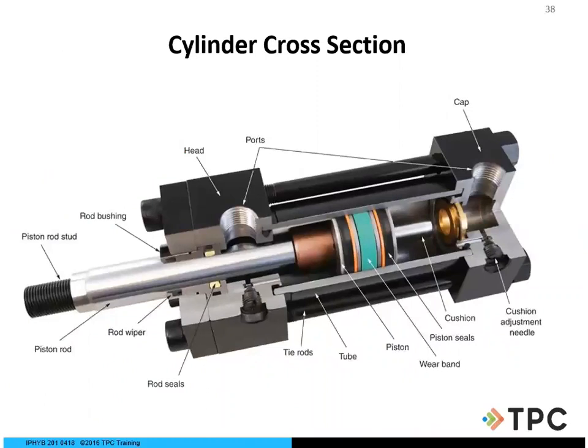And what about our actuators themselves? What about the cylinders? So we definitely need to maintain those. We need to repack them if they leak. We have to make sure that no contamination gets inside of here. And so we have to look at our rod, our packing, what type of packing. Remember I said before about what type of rubber, what type of seals we have, what temperatures we are working with, actually the fluid itself. And so there have been a lot of cases in past history where the hydraulic fluid is not compatible with the seals that are in the actuator, that are in the cylinder.